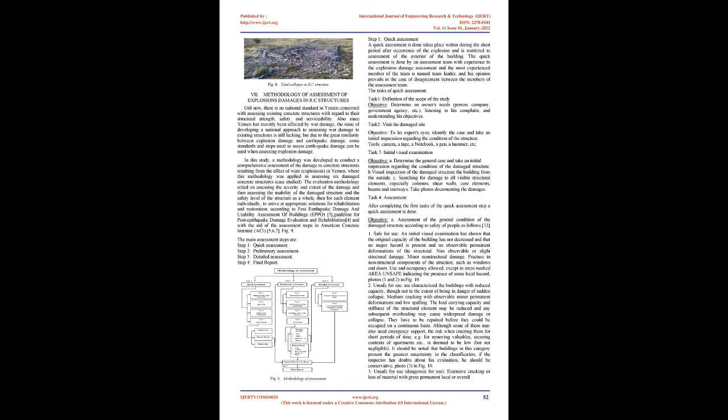D. Separation in linear elements. As a result of the intensity of the force of the explosion wave and the fragments flying from the explosion or from other damaged elements, linear elements such as beams and columns are subjected to shear forces greater than the resistance of these elements, which causes fracture, in addition to steel yielding and permanent deflection with large cracks. Fig. 5.